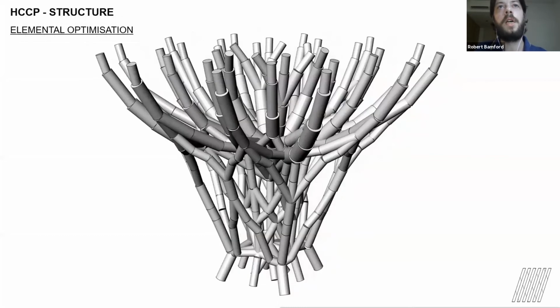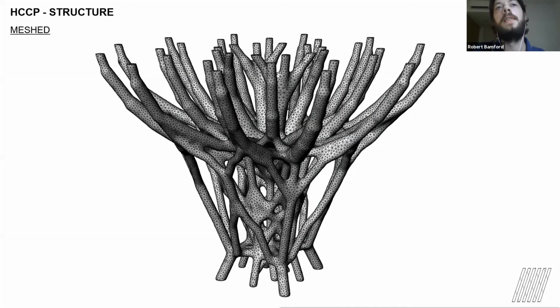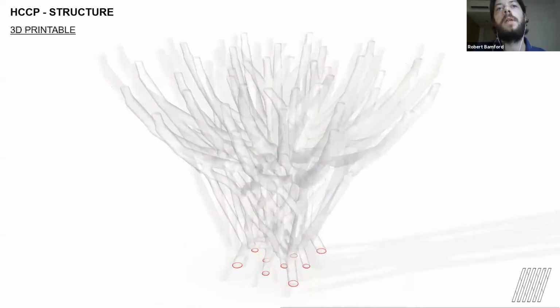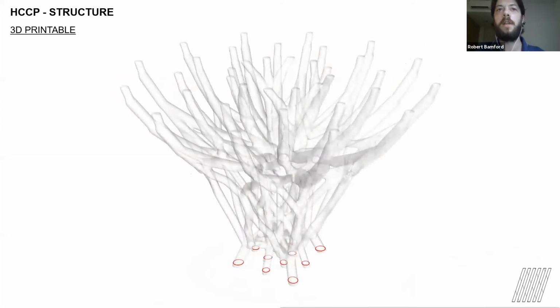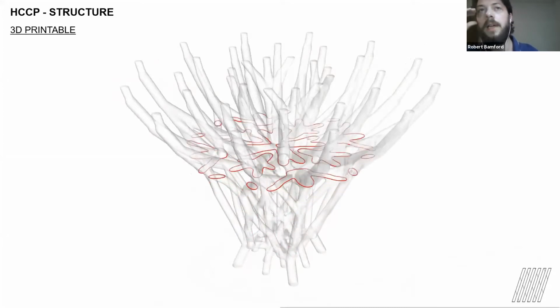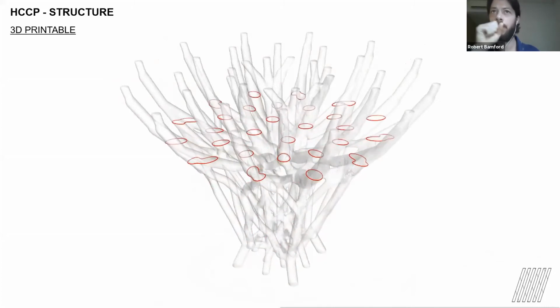Each of these segments has been analyzed through ETABS, and this is the direct size output from there, which we can then post-process to create our printing mesh. And then this becomes the 3D printing path coming up through the structure. You can see the underlying very regular cylindrical geometry of each of these elements, but as a whole, super complex geometry to realize.